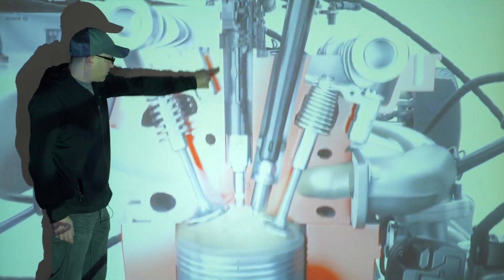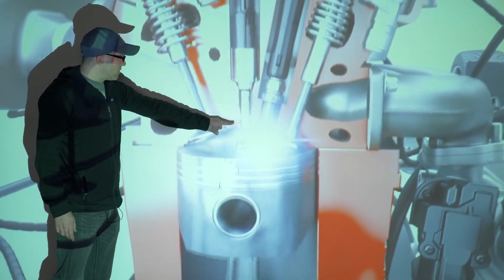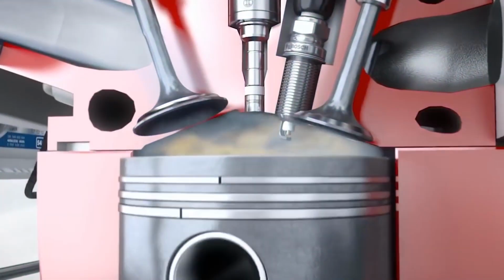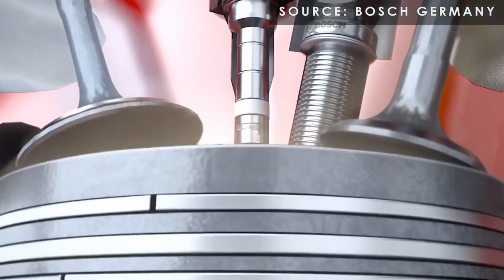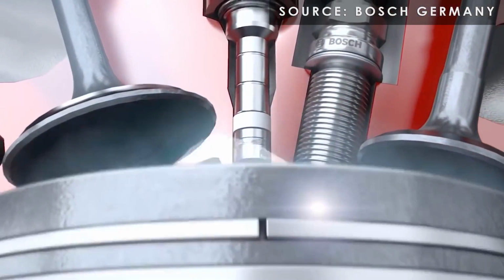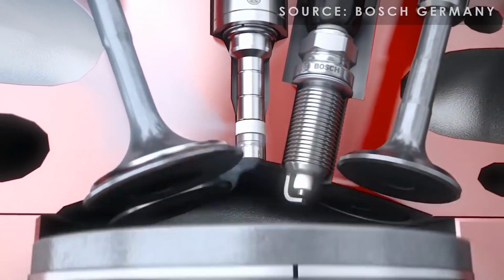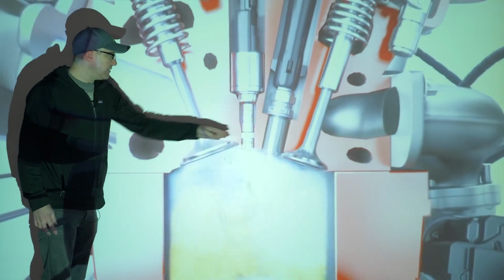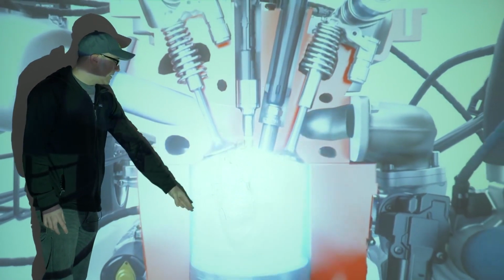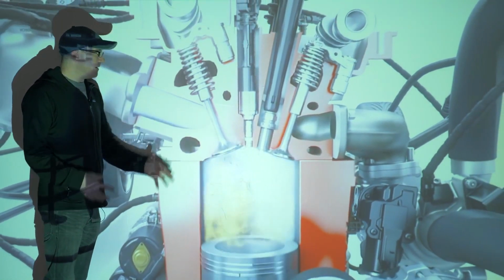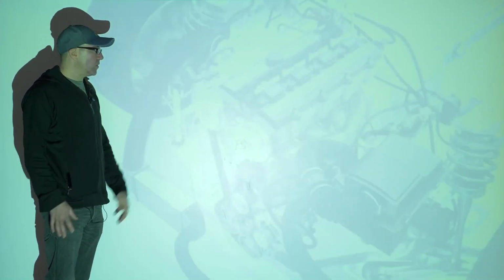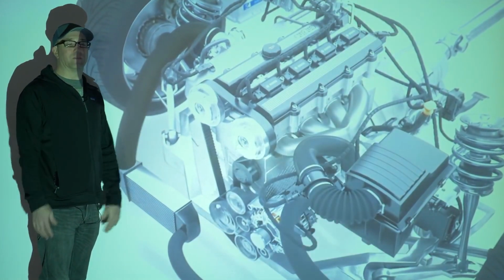And here is where the fuel is delivered, into a direct injector. It's called direct injection because the fuel injector is sprayed directly into the combustion chamber. There's your spark plug, there's your fuel, and that's what causes the combustion process. These are your intake valves that open and close, that is your piston, and that is the combustion cycle. So direct injection, or GDI, is nothing more than an injector being sprayed into a cylinder.